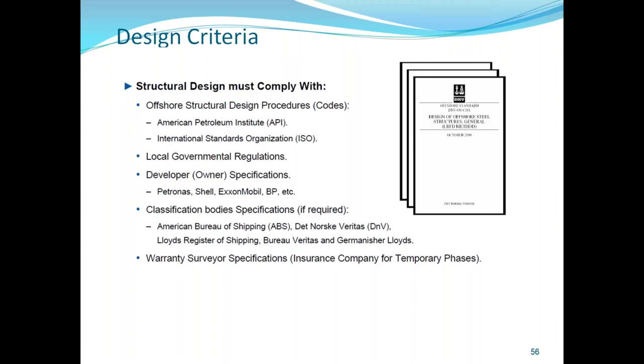So what about the topside portion? The topside portion is similar to your onshore structure design. That means you use EC3, or IS 800. But for the part below, whatever the jacket or the pile foundation, those codes will not apply, because the topside will not have that wave effect. We maintain the structure at such a distance that the highest wave will not reach it. So generally this topside structure will be designed as per IS 800 when it comes to India.